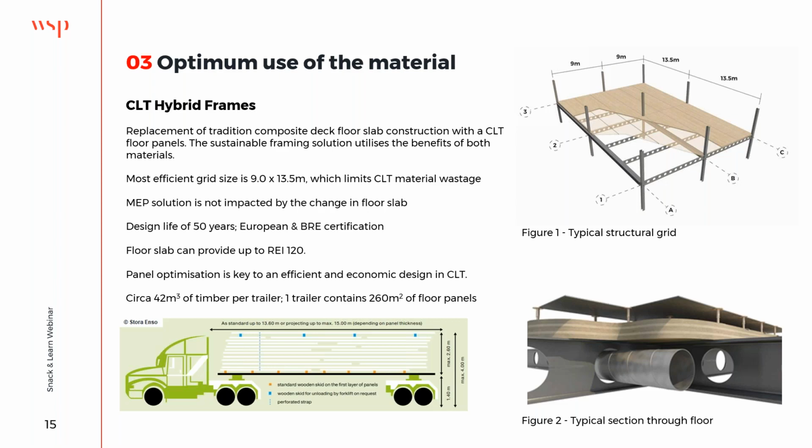So therefore, what we went to our clients and said, you know, we're developing commercial offices for you. We understand you've got ESG and sustainability targets. Why don't we look at a small change? So why don't we change the composite deck slab in a steel frame to a CLT slab? And in doing so, keep the same grid spacings that you would expect if it was the composite deck solution that you had previously. Keep the same potential for servicing through cellular openings in the beam that you would have if it was the composite deck solution.